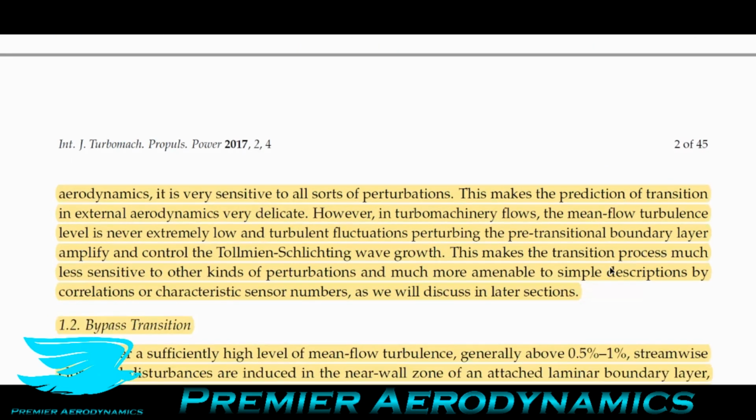So this is actually something we should talk about. How can we introduce perturbations to a system? Well, among other things which are very obvious, for example, if you have an object with a weight coming off of it, or a rough surface, or just any change, like a little bit of dust. Also, other things like if you have a table and it moves, or if you have sound propagating into the boundary layer, these can all trigger perturbations, and these perturbations can break down into turbulence, even sound, which we'll cover a little bit more later as well.